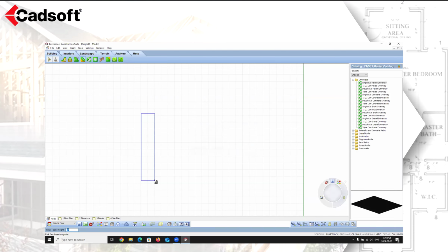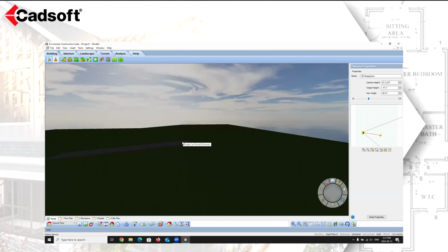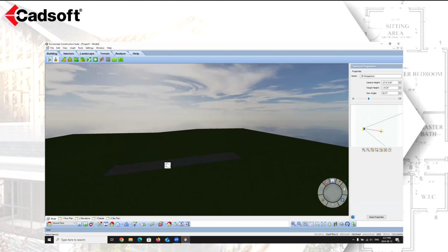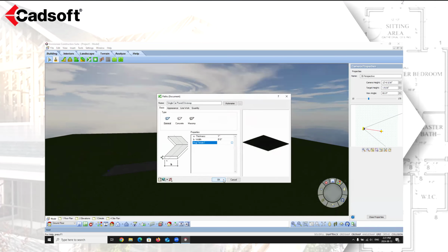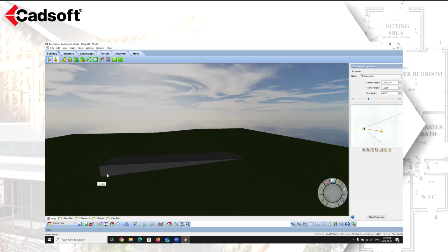And we'll say I'm going to start from here. And we're just going to go down like this. What it will do is it will take that path or that driveway and it will follow the slope as it moves. If you unselect this option, it will create a flat surface and it will try to fill in the void for you automatically. So you can again adjust this, use this tool to create any kind of pathway, driveway, sidewalk that you want in your design.